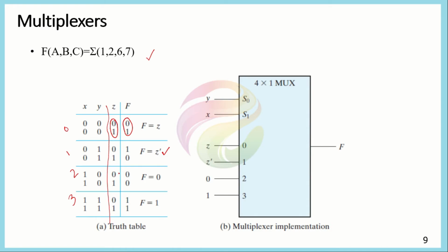So for these two combinations of 1 0 0 and 1 0 1, we just connect them using a simple 0 to the input 3. So this is the third input here. Now when we have 1 0 here, this would be connected to this I2 term here, which is connected to 0 because it corresponds to the function.